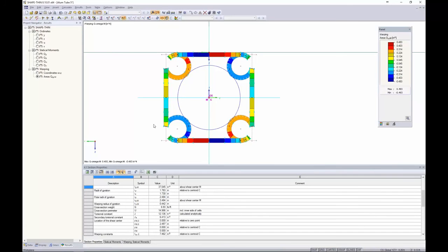And that's because I need to implement these C sub T elements within shape thin. And C sub T elements are just width to thickness ratios. Now, in order to implement C sub T elements, they can only be added to these straight line segments here. They cannot be added to these arcs. So if I was concerned with local buckling of one of these arcs, or had some other different shape where I had a rather large arc that I'd like to check local buckling, then it's suggested that you create multiple straight lines that compose those arc, and then you can create the C sub T elements.